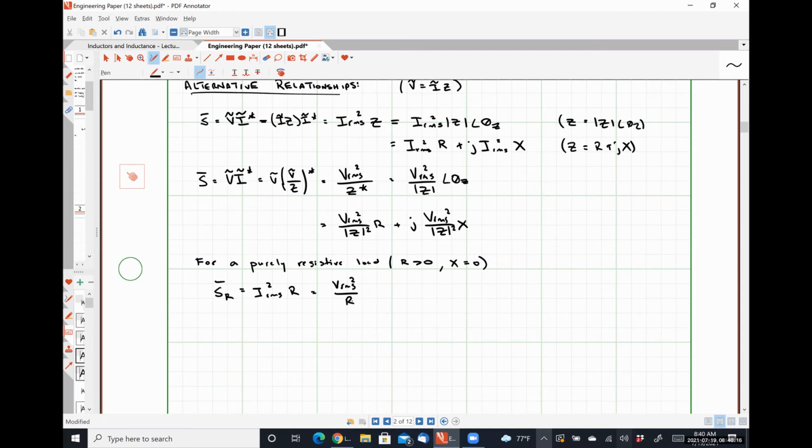So that's another added benefit of using RMS phasors. I don't know if you guys noticed, but there is a common factor of 1/2 that showed up in everything. And it's from that trig identity, where when we multiply cosine angle 1 times cosine angle 2, it's 1/2 cosine the difference of the angles plus 1/2 cosine the sum of the angles. Using effective values gets rid of all those spurious 1/2s, makes the analysis look much more like a DC circuit.